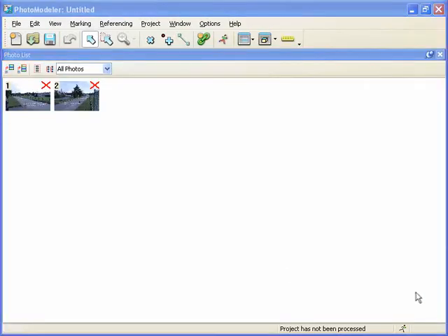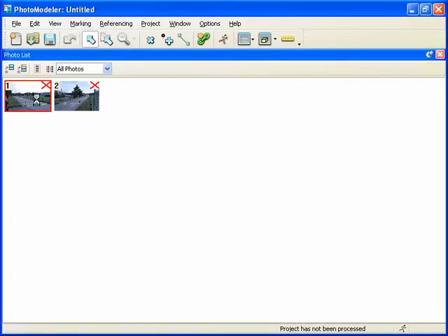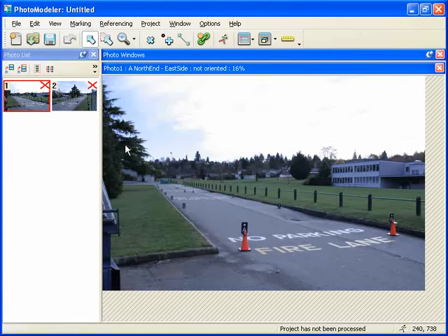While the scene does not have any vehicles, skid marks, or yaw marks, there is enough here to learn the basics of PhotoModeler. We will be solving for the positions of the evidence markers, as well as some simulated debris and some road markings. We start by double-clicking to open Photo 1. We switch to subpixel marking mode, which allows us to identify circular targets in images.